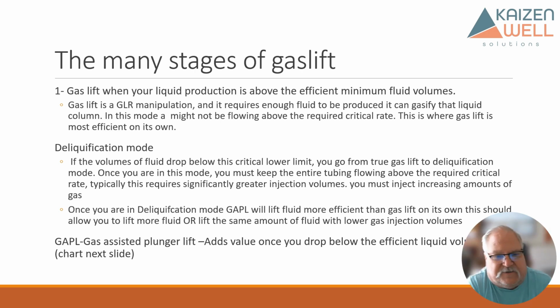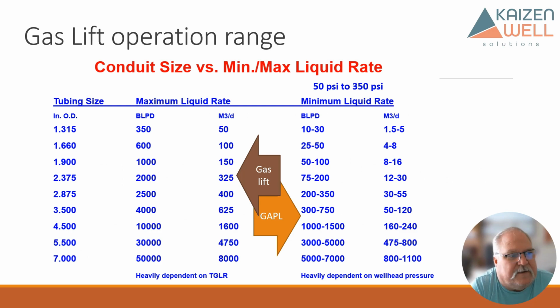And now you've got to replace that lack of liquid by high volumes of gas, and you basically got to go above critical to sweep the liquid to surface. A lot of people don't really realize that there are some pretty high liquid rates when you drop below that efficient rate.